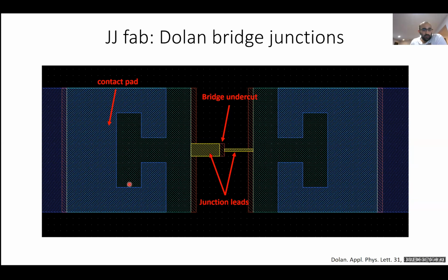Because you're doing an angled deposition, there's going to be a shift in the metal. So you also want a low dose exposure, given in red in these regions, in order to provide room for that shift to take place, and to make sure that aluminum doesn't get deposited on the sidewalls of your resist.